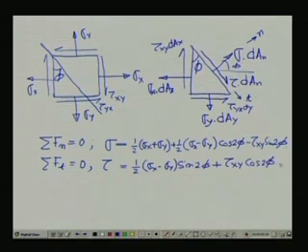cos 2 phi. While writing these equations, please note that we have taken this shear stress in these directions to be positive, meaning onto this x plane it is positive. If we choose any point within the body, this shear stress is creating a clockwise moment, and that clockwise moment is a positive one. This one is taking a negative direction, so we have a negative stress, because it is creating a counterclockwise moment.